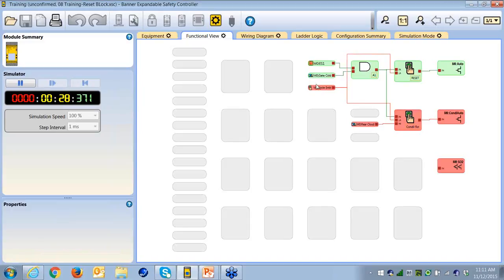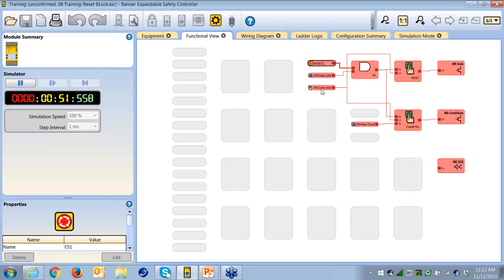So I've got this one set up in what they call the monitoring mode, and you can see it's working this way. It pulses. I push the button in. The reset doesn't occur until after I let go. This reduces the probability of somebody trying to build an automatic reset with the toothpick from lunch. There is, however, the possibility that there are some special conditions that I have when I want to restart.